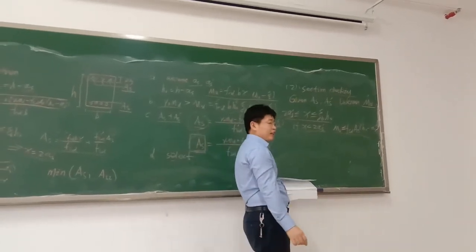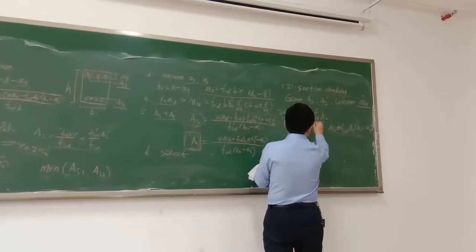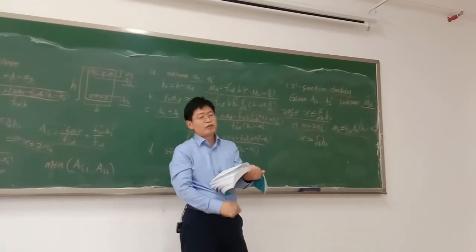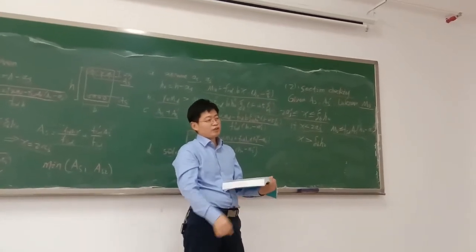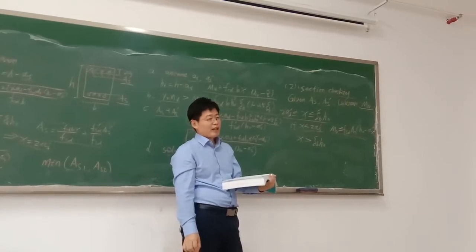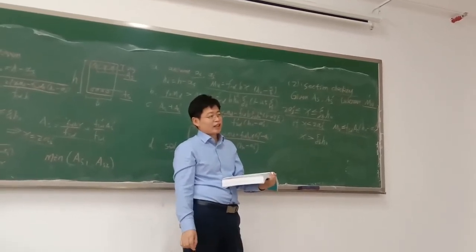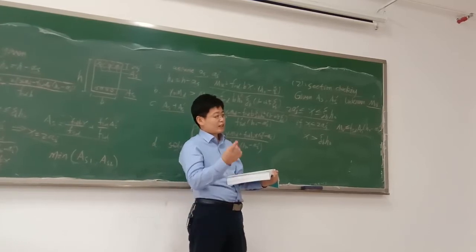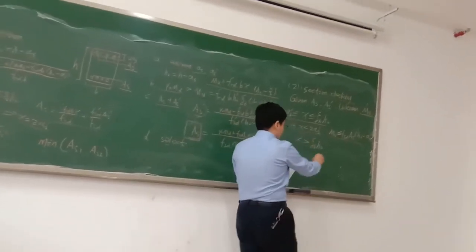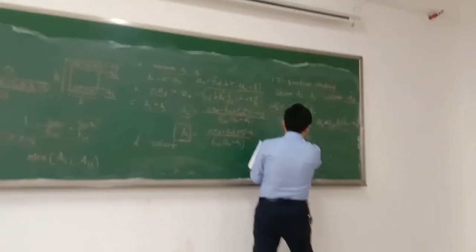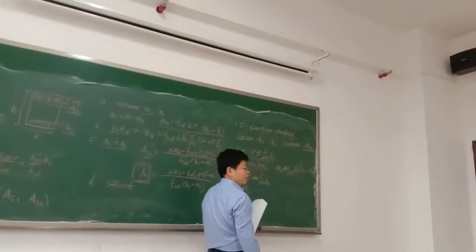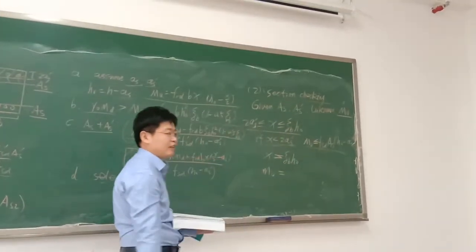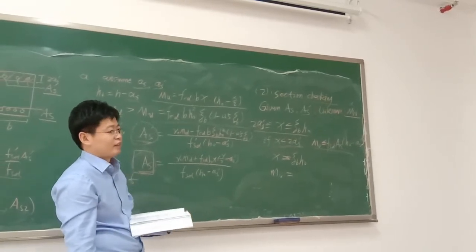Okay, so another situation: if x is larger than xb = ξb h0, that means your design is over reinforcement. For over reinforcement, how do we calculate? One option is to change your design to make it appropriate reinforcement. Another option is just to calculate the mu using x equal to ξb h0. Understand?